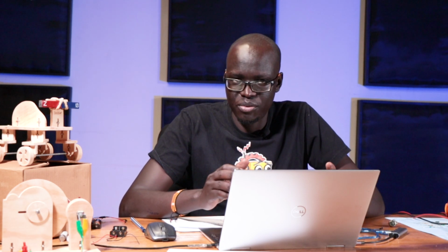We looked at it in the previous video. It's through a process called analog to digital conversion. However, the range of values coming out of pin number 11, the PWM, is going to be 0 to 255. So we can find a way to map the values, but for today's video, we're just going to do a very simple calculation. If you divide 1024 by 4, you roughly get 256, which will work for us for now. So we're just going to do a very simple division, and that's why you might see somewhere it might say divide by 4, and I will explain. So let's write the code.